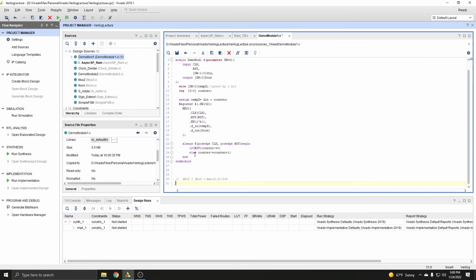And multiplication is even more straightforward. If you had a 4-bit times a 3-bit, it is simply the sum of the two bit sizes. Therefore, it is a 4 plus 3-bit number, which would be a 7-bit number. Or 4 times 3, and then 4 plus 3 at the end gives you a 7-bit number. And that is what you need to represent the output.